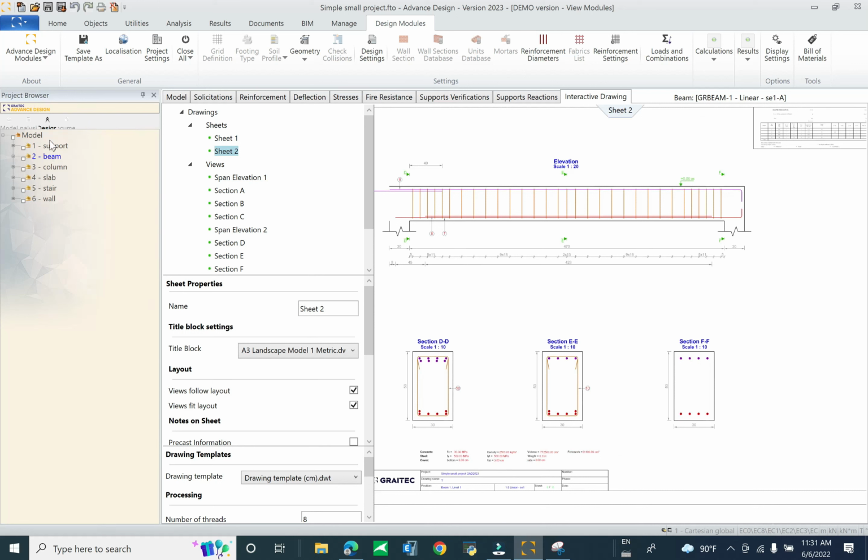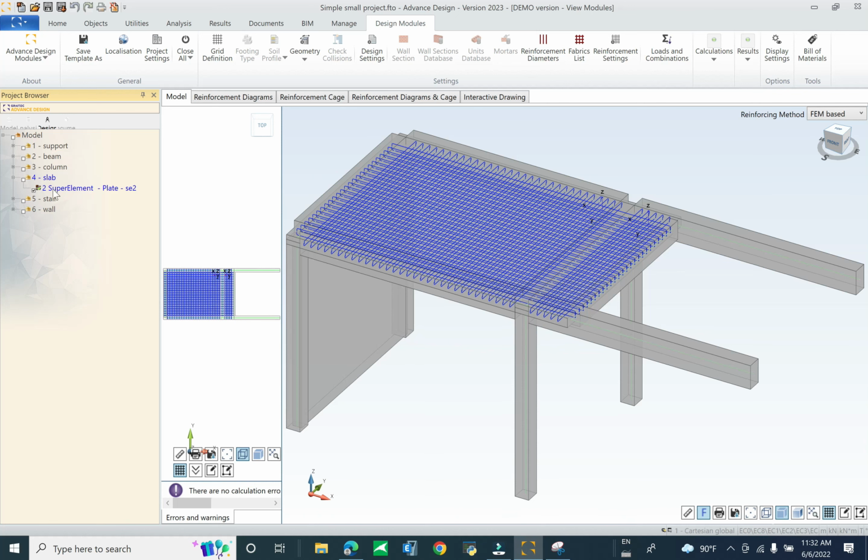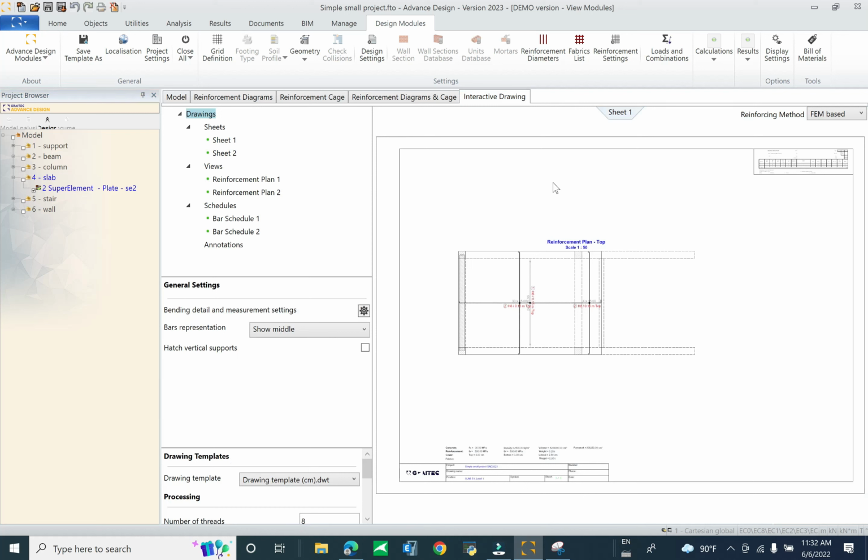Now you can check in the design, and for the support, the highlight in blue is the active design beam. You can check on the slab, and you can double click on the slab if you want to come back to review analysis and design. You can select the slab, and you also can select it on the interactive drawing because you have analyzed and designed the slab already.